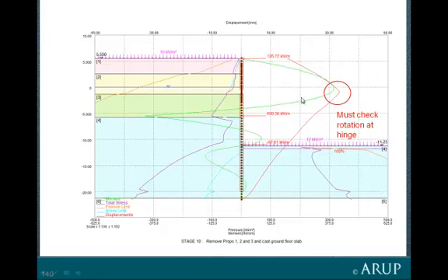It's dropped at this level but increased at the prop, so now you have to check it at both locations, and it's around about 400 kilonewton meters per meter in both cases. Note that it may be more critical here. The bending moment requirements are more critical at prop position, where there's large shear forces, than they are at mid-span. So the important place to check the bending moment would probably be here. Whether this process will be acceptable in the future with more flimsy yet stronger sheet pile sections remains to be seen. This only refers to ultimate limit state calculations. You can't have plastic design at serviceability level.